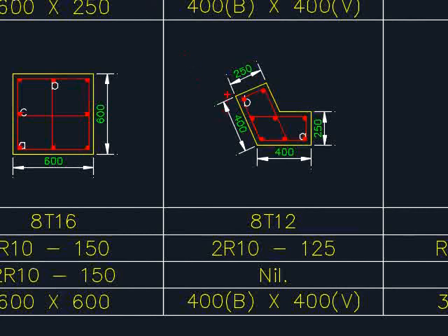You cannot simply put any 4 out of 5 corners here, as you are unable to maintain the shapes. Based on the shape here, the reinforcement bar needs to be at every corner of the side of the column, which in this case means 6 reinforcement bars will be required.